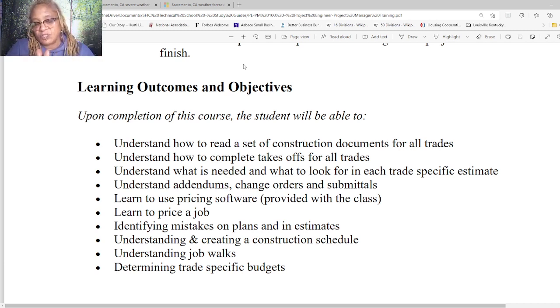And two, what's most important too on a financial end, as a project manager, you're able to take the construction schedule and not only line up time and operation, but also line up time, operation, and money. And so you know at each hour of each week how much money you have earned, meaning you have already made by producing or building that building. So how much of the building have you already built, and how much should you be getting paid for, because that portion of the building is built.